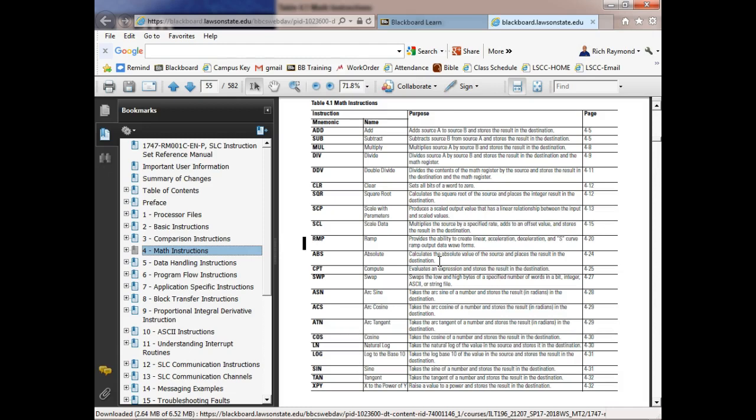Well, probably not. Right, so the number of math instructions that's available to you would be determined by the PLC that you're using, and it'll pop up. So this is one of the things you do when you start RSLogix and you create a new project. The first thing it wants you to do is select a PLC, a CPU. And what do you think you're doing when you select that CPU? You're bringing in the instruction set for that CPU, right? You understand? So that's what's really neat.